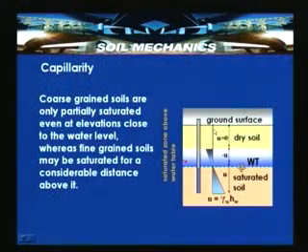That means that this ordinate, Hc, is nothing but the negative head which is kept above the water table, that is minus gamma W Hc, which is nothing but the negative pore water pressure. Then immediately the pressure can be dropped to something like zero pressure. So, this negative pore water pressure is also referred to as suction pressure. So, U or Uw is also minus gamma W Hc, which is also referred to as suction pressure. By substituting the value of Hc, we can also obtain this suction pressure.